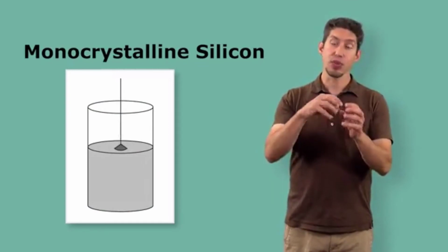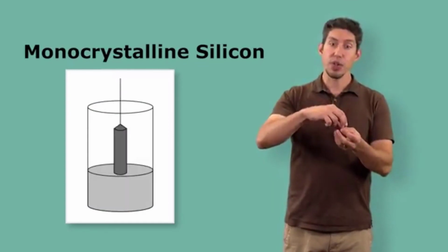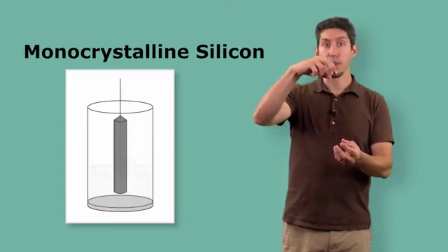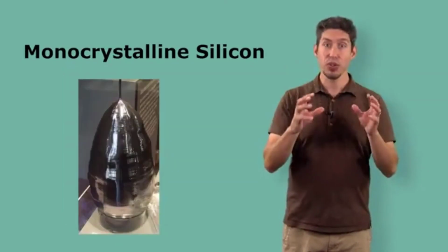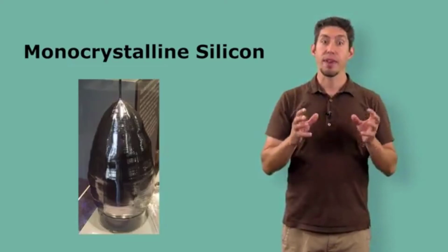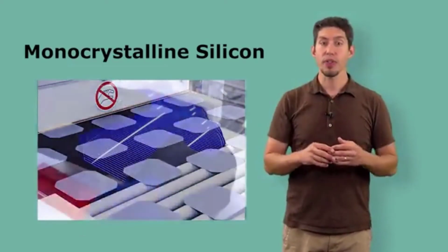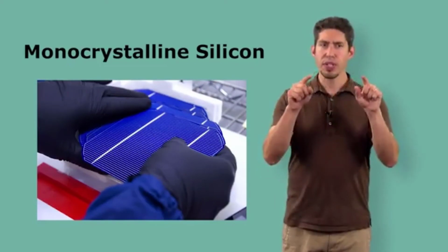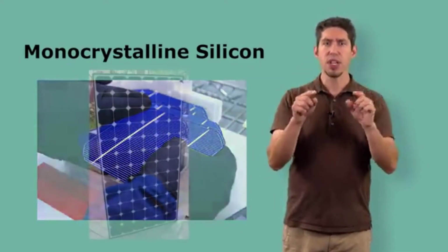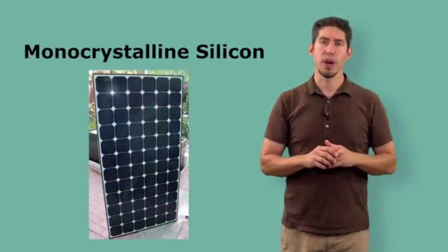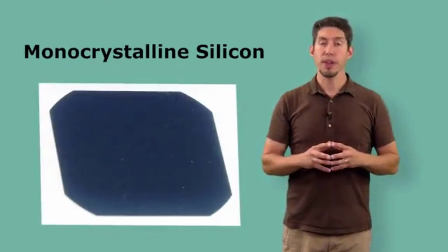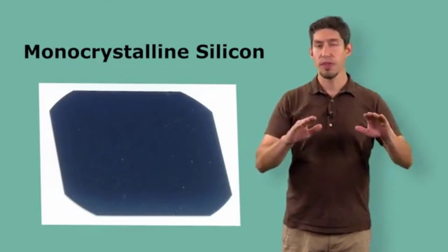That silicon is then grown around the seed and is slowly pulled up into what's called a boule, which is one single crystal piece of silicon. That round boule is then cut into thin slices, and that round shape often results in cells with rounded corners or rectangles, often seen in those monocrystalline modules. The overall appearance of silicon is uniform, flat black, and non-flaky.